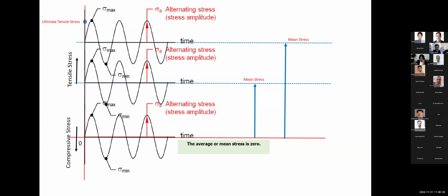What will be the effect of the mean stress on the S-N diagram? That is, the number of cycles and the amplitude of loading. And this is typically signified in this particular diagram. So this is a typical S-N diagram, where we are plotting sigma stress amplitude versus cycles to failure for 3 different values of mean stress, M1, M2, M3, where M3 is the largest mean stress.